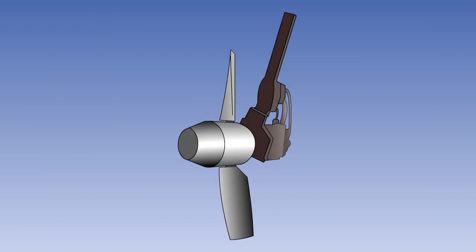The ram air turbine, or RAT, is a propeller-driven device which can be lowered into the slipstream when required. If fitted with an AC generator, it will produce an emergency source of AC power. It may be known as an LRAT. On many modern aircraft, the ram air turbine is used to drive a hydraulic pump, rather than an electrical generator.